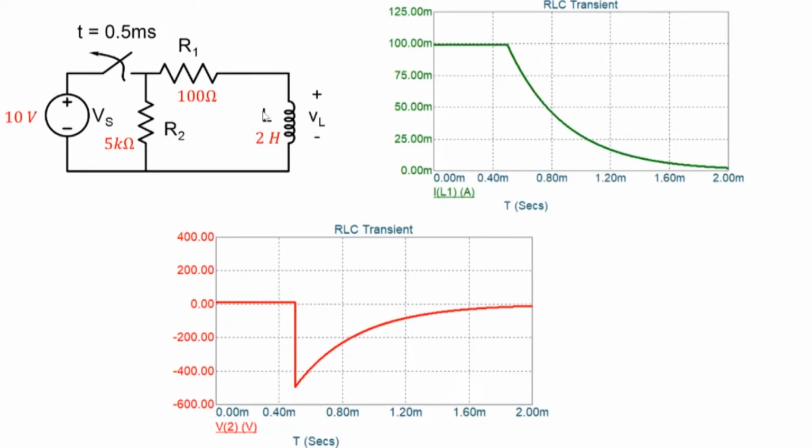A principle like this is, for example, used in tube lights. Tube lights require a higher voltage momentarily to cause a discharge in the gas. We have a choke, which is an inductor here, and a principle like this is used to generate a high voltage to cause a breakdown in the gas and result in current flow.